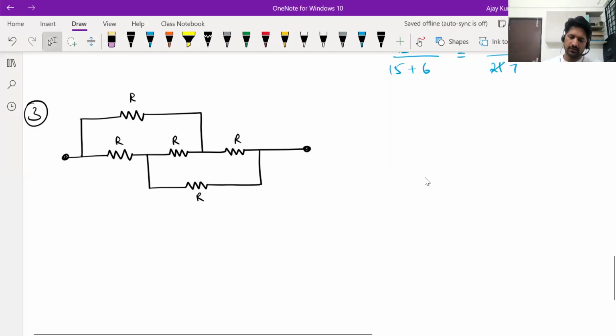First, is this a Wheatstone bridge or not? You check carefully, you will notice that there are no 2 resistors in series, no 2 resistors in parallel. Totally, there are 5. So it has to be a Wheatstone bridge. There is no other possibility also. If you want, you try to draw a network of 5 resistors, no series, no parallel, not a Wheatstone bridge. You can't. Try to draw it like that if you want. You'll understand whether it's possible or not.